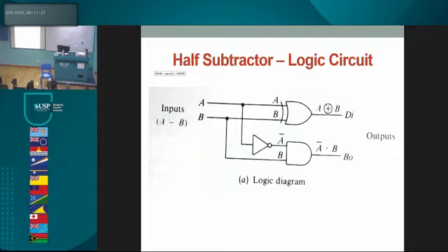Same problem with half adders. What is the problem with half adders and half subtractors? They can only handle 2 bits, bit A and bit B. No connectability to another system. We have to develop that. Right? We can't bring in a carry out of something else and plug it in here. Okay, so if you guys are familiar with a computer or something else, there's no expansion port over here. You can't expand the system. We have to artificially do it.